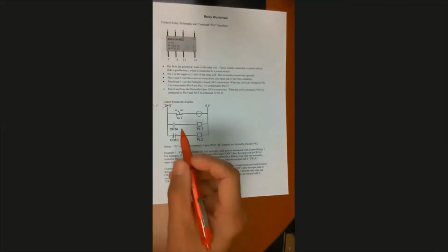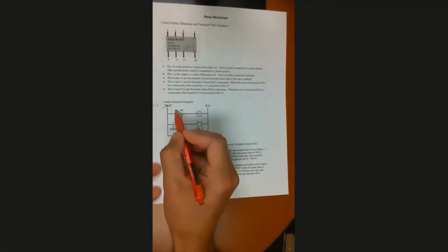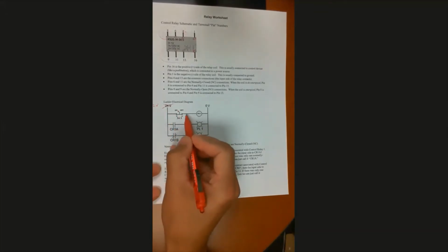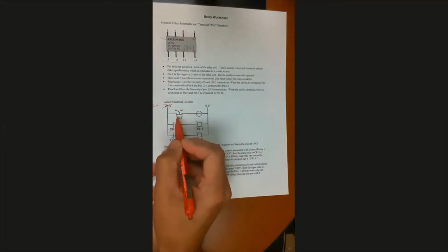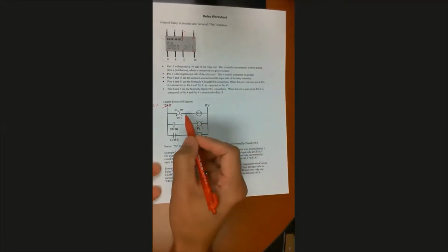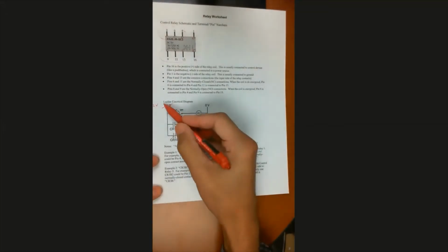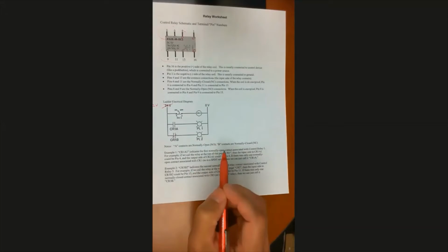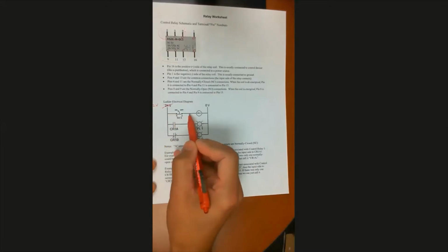Okay, so basically the way it's drawn here, the way it's going to work is when it's on, we're going to have continuity through here, through this rung. When it's off, we won't, because there won't be connection from here to here. Okay, so when it's off, I like to start actually when it's off. So let's say we've got 12 volts applied here, but we're not turning this to on yet. So this is off, okay? So we don't have continuity through here.